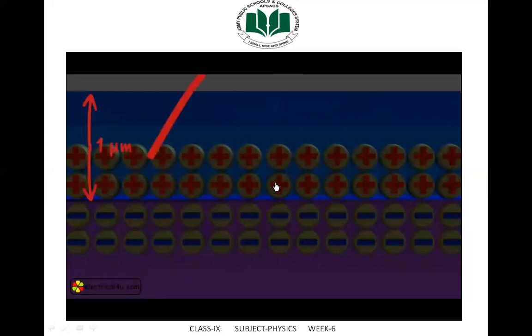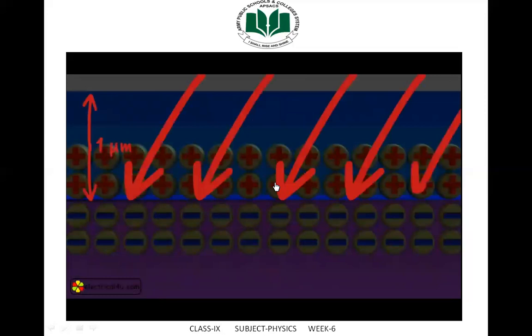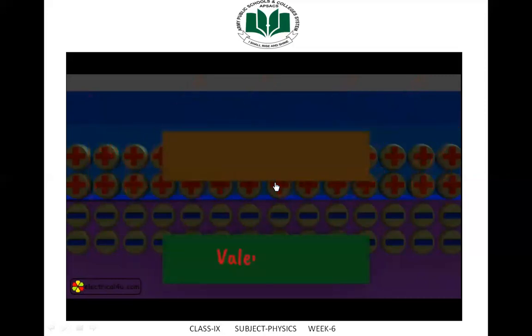So, light photons can cross the layer and strike the junction. The energy of each light photon ranges from 2 to 3 electron volt, approximately. The band gap between the valence band and conduction band is about 1.11 electron volt in silicon semiconductor at room temperature. Hence, light photon energy is sufficient to break the covalent bond in the silicon atom to produce a free electron-hole pair. This is because the energy associated with visible light photons will excite the valence electron to jump out to the conduction band as a free electron, leaving a hole behind it.